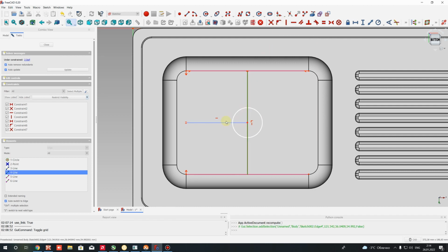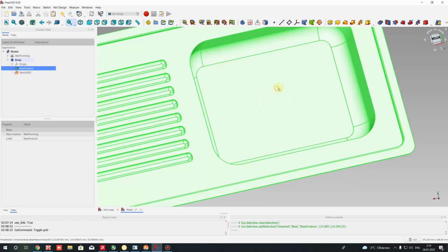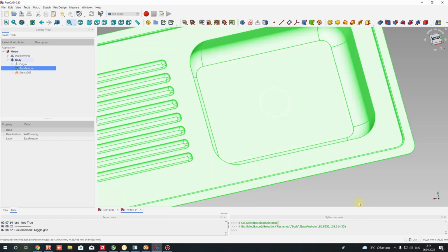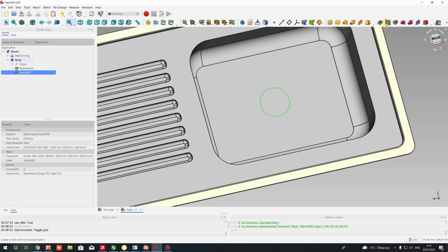And these blue lines means that if you will close a sketch, you can see that we have only the circle. Blue lines is hidden, and it means that it doesn't crash our creation of extrusion operation. Blue lines is ignored when we have it, and white lines are working like a physical sketch for creation of models, extrusion or CAD operation, another thing. For example, here we have to choose this circle and create a hole.